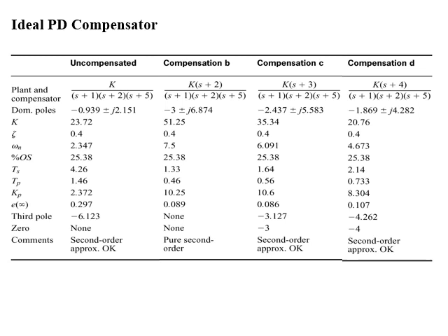Students, in this table, the steady state and transient characteristics of the uncompensated and PD compensated systems for a zero at locations of -2, -3 and -4 are summarized. You will observe that in all the cases we have the same percent overshoot, while other transient features like settling time and peak time increase as the zero moves from -2 to -3 and then to -4. In the second case, we have a zero at -2 which cancels out a pole at -2, so this gave us a better second order approximation.